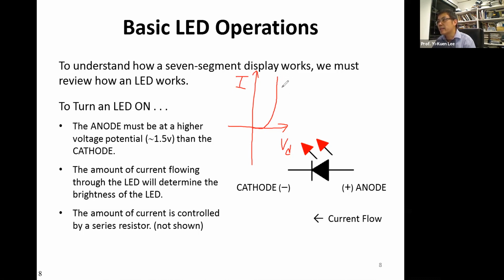In this case, very possibly, if the voltage is much bigger than the threshold voltage, VT, then you turn on the LED. But if your voltage is too high, what happens? What do you think? If the voltage is high, you can see this is an exponential function, and what happened? Actually, it's very possible it may burn your LED.